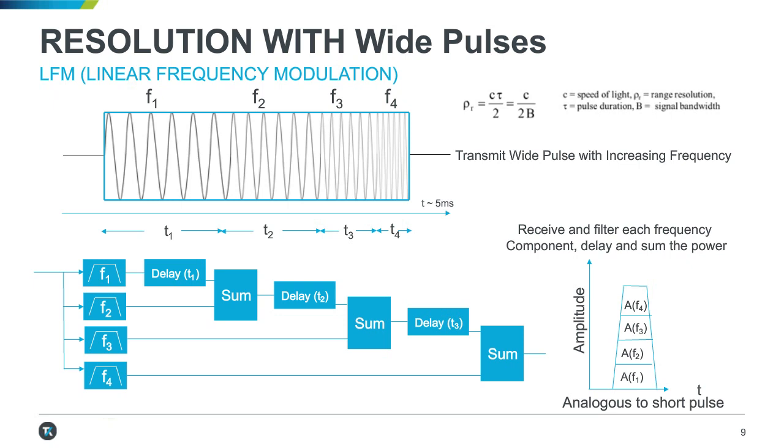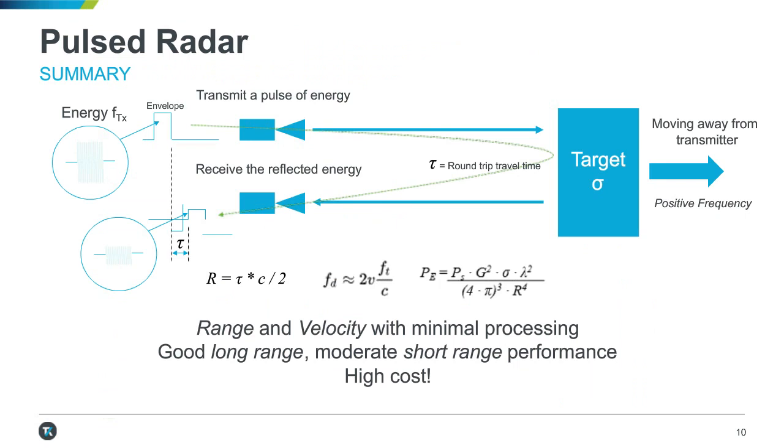So we've learned a few things in the last couple of slides. All around pulse radar, we can transmit a pulse of energy. It reflects off a target. The width of the pulse is going to determine if you can discriminate between multiple targets that are close together. The frequency of the returned pulse and how that differs from the transmit frequency, I'll tell you what the Doppler is.